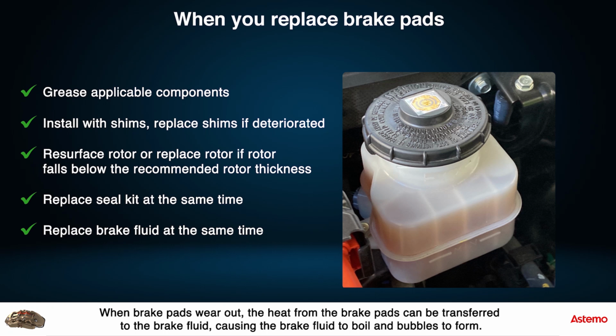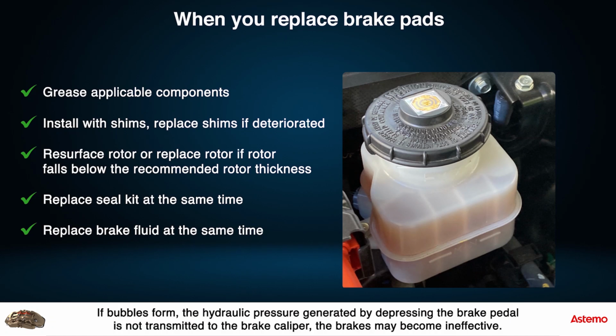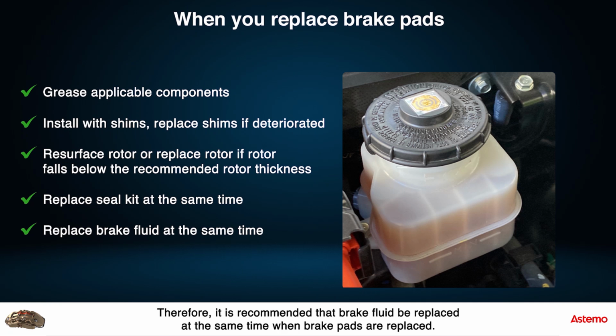When brake pads wear out, the heat from the brake pads can be transferred to the brake fluid, causing the brake fluid to boil and bubbles to form. If bubbles form, the hydraulic pressure generated by depressing the brake pedal is not transmitted to the brake caliper, and the brakes may become ineffective. Therefore, it is recommended that brake fluid be replaced at the same time when brake pads are replaced.